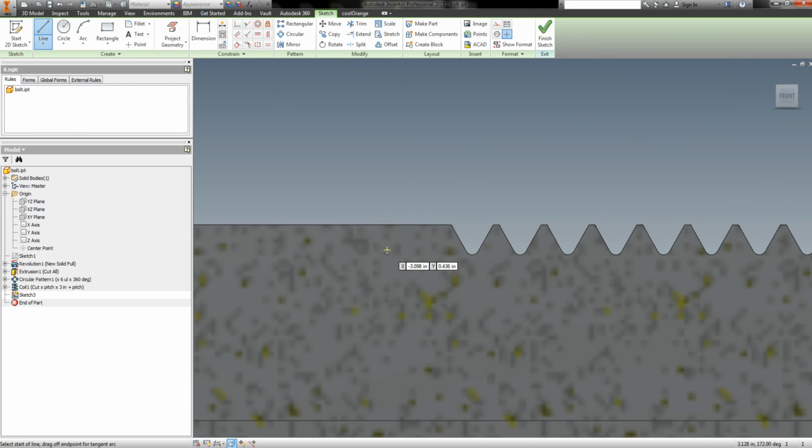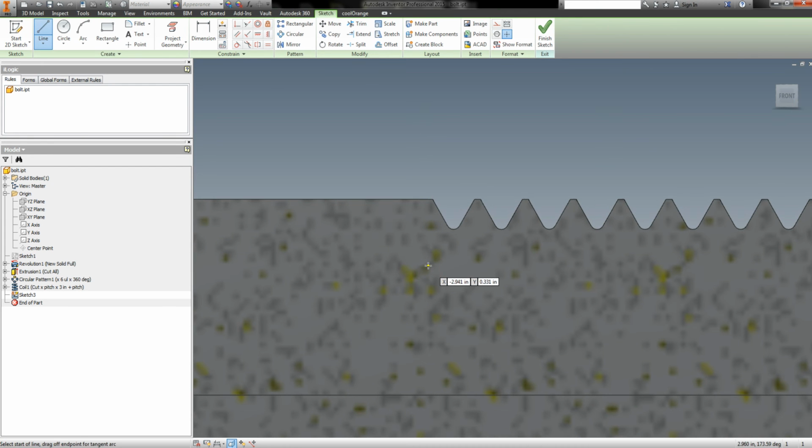So in this sketch, let me hit F7 to cut my geometry here. Now your relief groove size may change based on your part, your threads, and the cutting tools used. So I'm just going to throw numbers at this relief groove in order to make it. Consult whoever you need to find out if your relief groove, if you're machining this part, needs to be bigger or not.